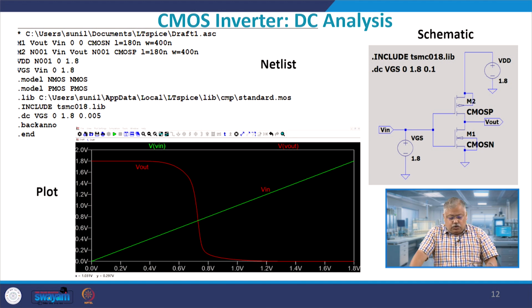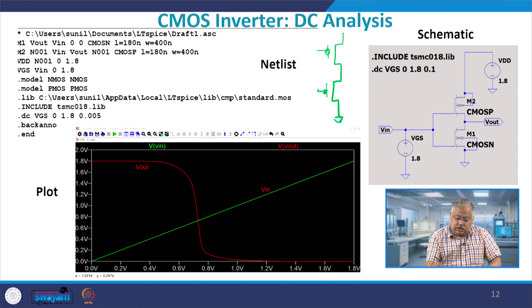This shows you the DC characteristics of a CMOS inverter. If you look carefully, there are two devices, because now you will have an NMOS pull down device and a PMOS pull up device, which you already know from when we were doing it. So, it is something like this which you will follow. So, this is my PMOS and this is my NMOS. You apply a VG here and you try to take the voltage at the output here. This is V out and this is your C which you see.